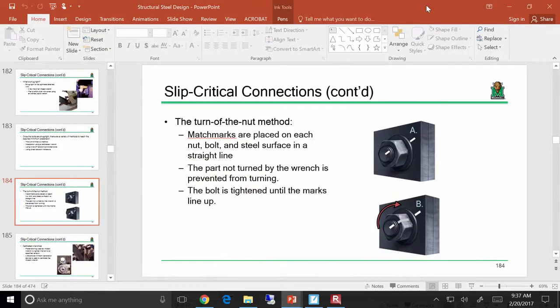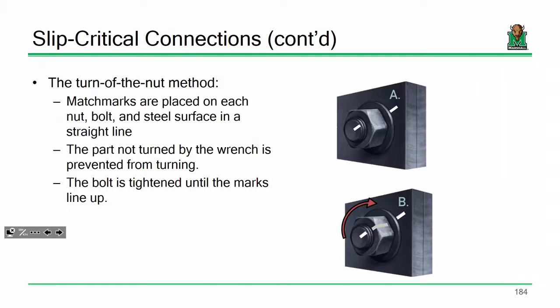They're 1/16 of an inch. The slide says use oversized or slotted holes. That's a good question. When I say oversized or slotted holes, I'm talking about things like on a bridge where you have an expansion bearing. To allow a little bit of potential movement, you might have a slotted hole. More often than not, in most structures, we try not to use them.